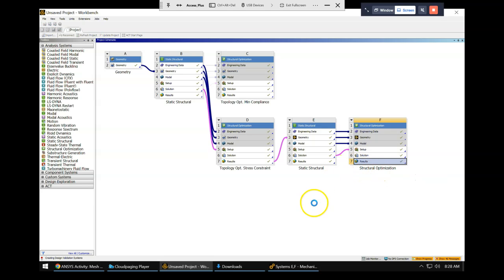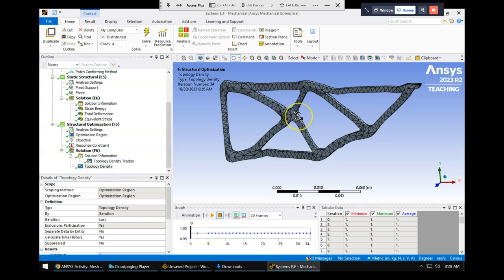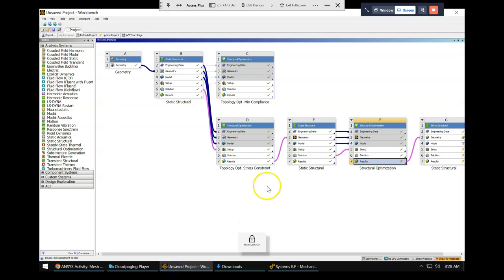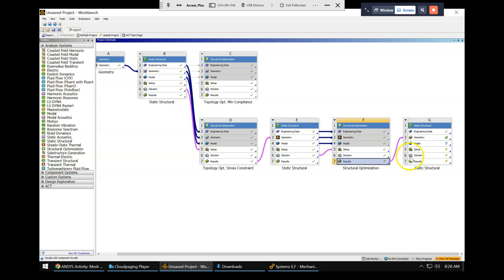So click that. That'll take a little bit to update. We may see the workbench window pop up. What this is going to do is generate a solid, taking our mesh from our mechanical window. It's going to make what's called a faceted solid in SpaceClaim or Discovery, which is what we'll be using. And then in order for that to work back in Ansys, we need to convert that to a proper solid that Ansys understands. So right now it's generating. Okay, looks like it went through.